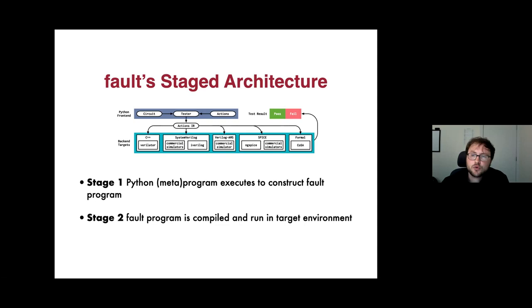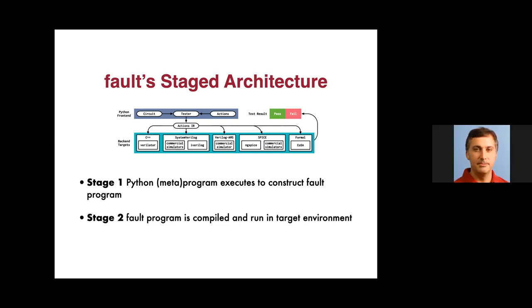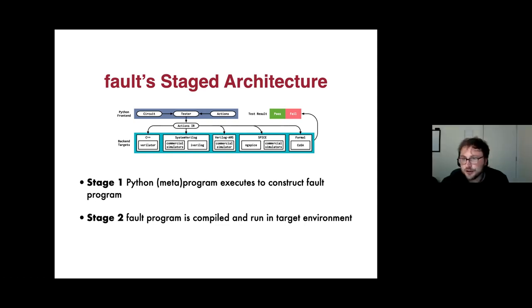So I mean, if you're not changing the circuit itself, then, for example, in the Verilator test bench, which is kind of our main development tool, we try to use Verilator as much as possible until we really need to use an actual commercial tool. So we can leverage the Verilator generated circuit while still changing the test bench, for example. So a change in the test bench does not necessarily require a full recompilation of the entire circuit.